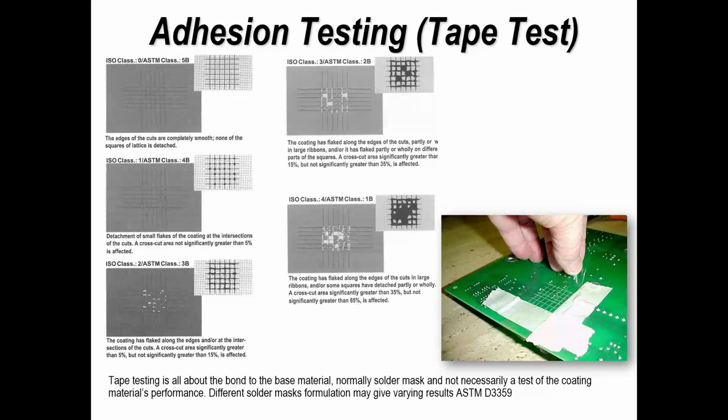Now, a lot of people never specify the solder mask type they have on their boards, and they don't know. They know it's green, and they know it might meet the specification of IPC, but they don't know what it is. So if you're not in control of that, that's a negative. You, as the designer, the assembler, the quality department, need to know, what is it? Is it a Peters mask? Is it one of the other suppliers that are out there?